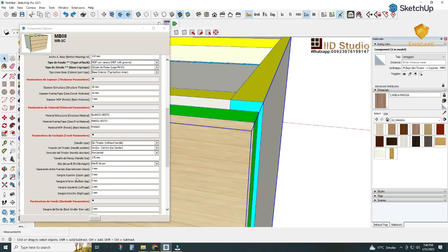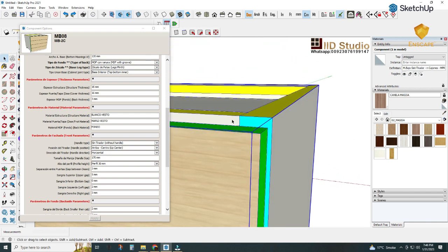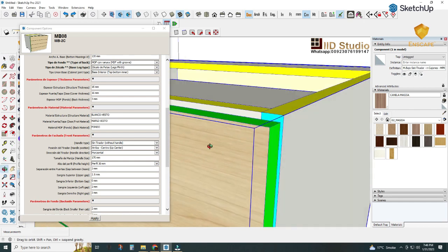left gap, sorry, upper gap. First of all, this upper gap. So if I want to change it to 2.5 centimeters for Corian or something else installing at the top, so you have to reduce the door size from the total size. So let's change upper gap to 2.5 centimeters, 25 mm.